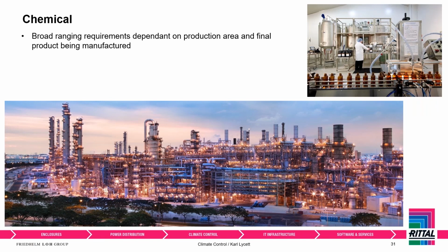Okay, next one is chemical. Again, I know that's a very catch-all sort of term. There's a broad range of requirements there because it really does depend on which area of the chemical environment you work in, and also what product's being manufactured. However, we tend to, as a generic standard, offer stainless steel, because if there's chemical vapors in the air, we need to protect from those because it attacks mild steel. So stainless steel is the first port of call.